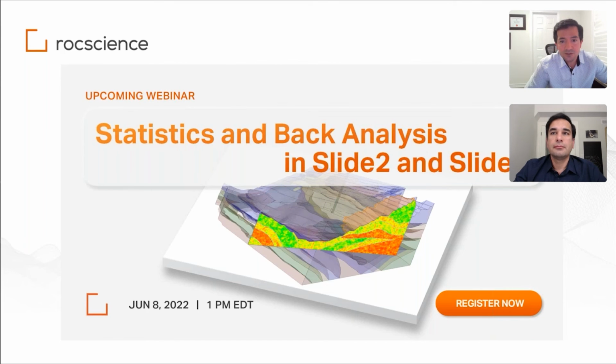I see another question from Alireza: how do you compare this model with the hardening soil model? Hey, the same name, Mirdamadi. NorSand compared to hardening soil: first things first, there is no state parameter in hardening soil. And also with hardening soil, you cannot do softening behavior. And if you would like to simulate static liquefaction, it would be really hard doing it with hardening soil.